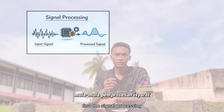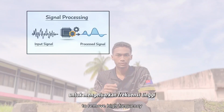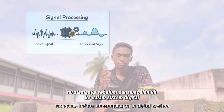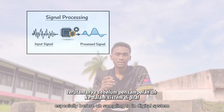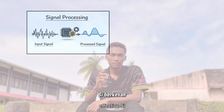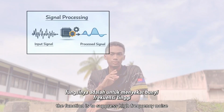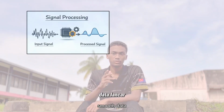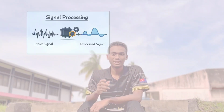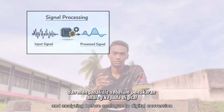First, signal processing. Low pass filters are widely used in signal processing to remove high frequency interference or noise from signals, especially before sampling in digital systems, and it helps prevent unwanted frequency components from affecting system performance. The function is to suppress high frequency noise and smooth data or waveforms used in communication and process control. Lastly, prevent aliasing before analog to digital conversion.